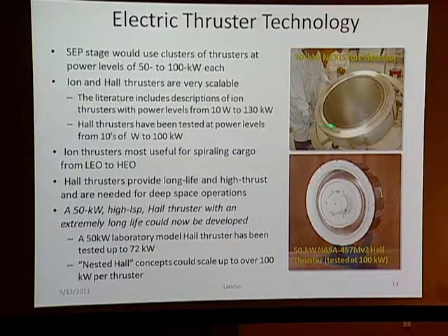So we have big ion thrusters, which again are the ones on the higher ISP range. But we also have Hall effect thrusters where, to make a long story short, you get a plasma in this torus here, and you set up a magnetic or electric field between them, and you get a Hall effect that shoots stuff out the back. The nice thing about these, they do operate at a lower ISP, but for a fixed power, you get a higher thrust, which means for fixed flight time missions, they come in handy in order to get the job done in a reasonable amount of time.